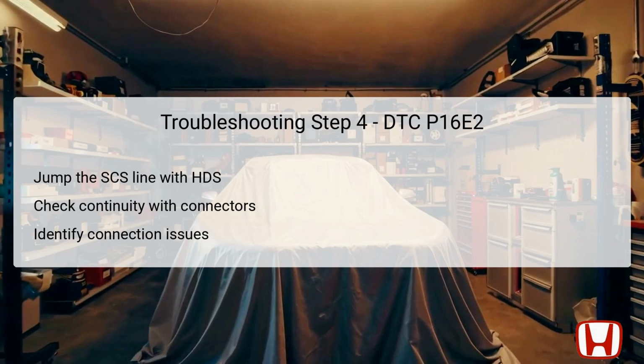Once this is completed, you will check continuity again between the alternator 1P connector terminal and body ground, following it up by disconnecting other connectors step by step: the PCM connector B, battery fan motor connector, and DC-DC converter connector. Observing whether continuity disappears once one of these connectors is disconnected will inform you about any additional faults on the